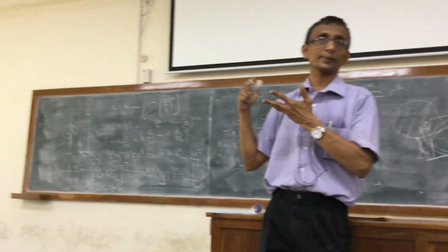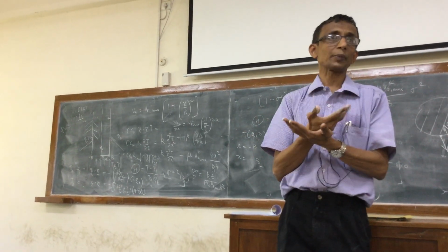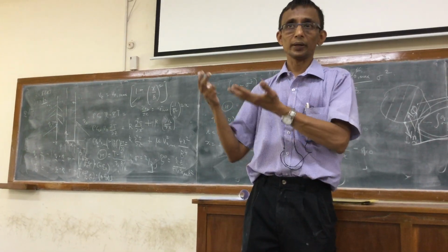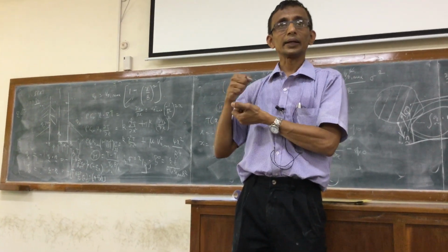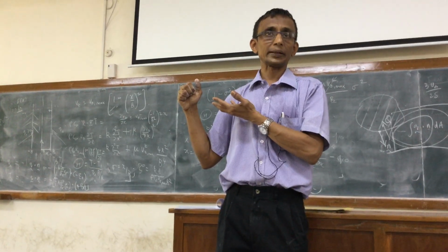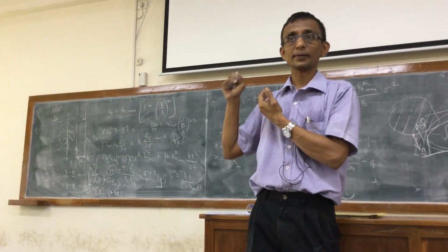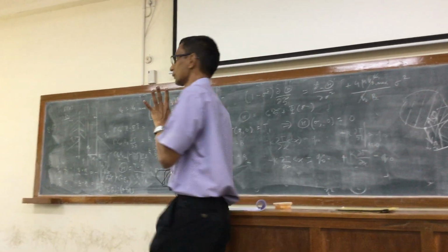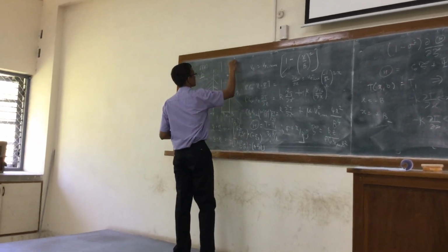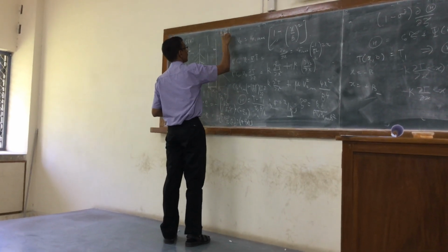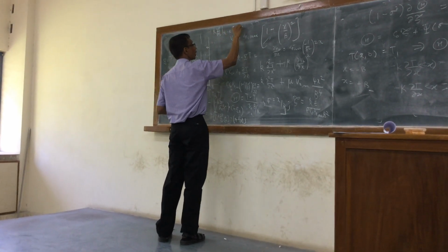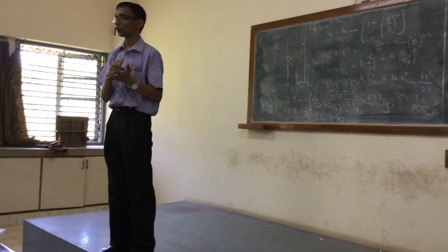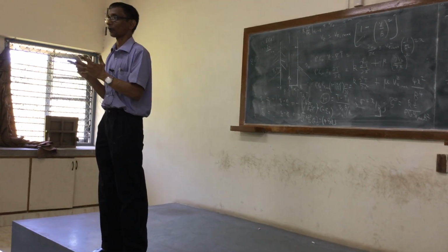You can consider both cases here also. Let's say heat is being removed. What will be the boundary condition? In the cylinder also, there is only one boundary, r equal to R_c. The heat is being transmitted. You can consider separately the cylinder surface with heat being removed and convince yourself there. For both cases, the boundary condition would be k dT/dr at r equal to R_c is equal to Q naught. Now for heat being removed, Q naught will be negative. For heat being added, Q naught will be positive. That sign convention also you have to remember.